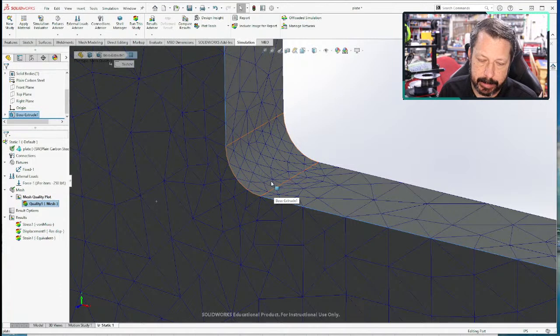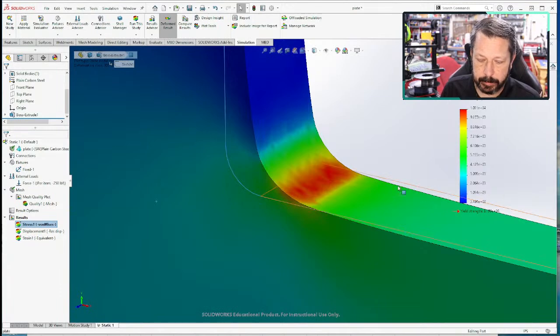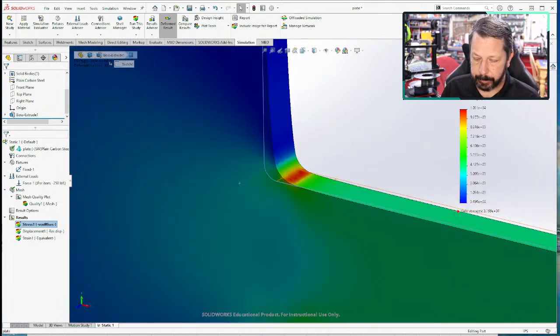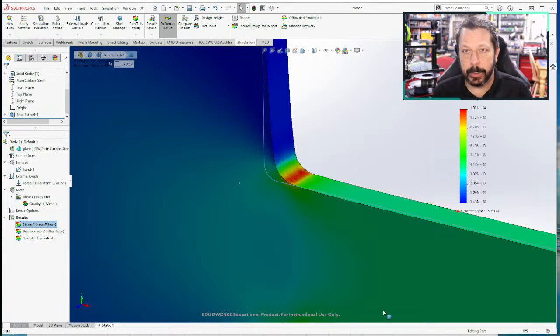And I could still have way more elements in this transition area, but the other numbers around here are in the 8,000 range, and even 10,000 is not that far from 8,800. So I'm thinking that we're accurate with both by hand and our finite element model. Neither one is 100% correct.